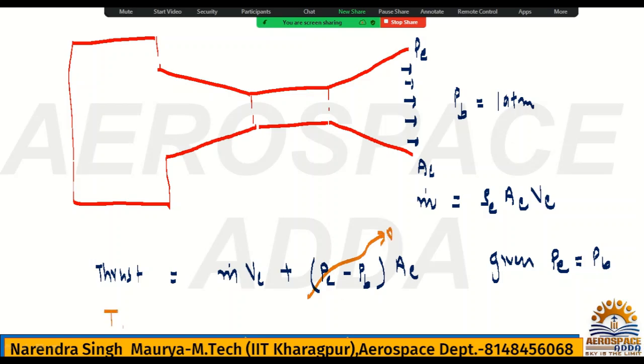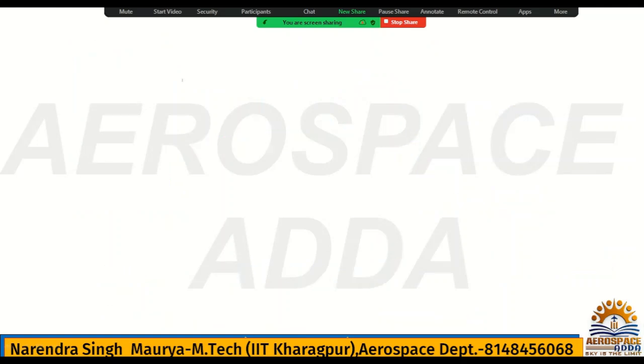So what is the thrust? M dot VE. And m dot is rho E AE VE, into VE. So thrust is rho E AE VE square.